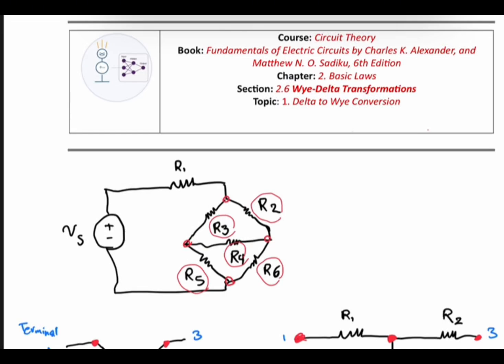In today's video, we'll dive into an essential technique for simplifying complex resistor networks. A Y-delta transform or delta-Y transform, which we also show as delta-Y or Y-delta transform, is the topic that we are going to cover in this lecture and the upcoming lecture.